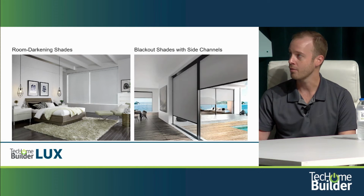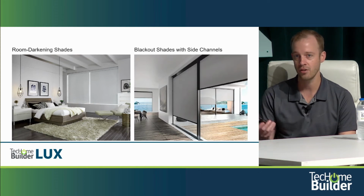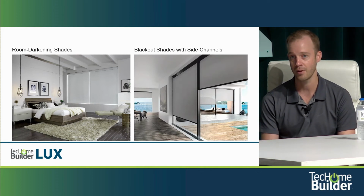Full blackout lives in side channels, right? So that's a conversation that also has to happen early on in the design process because these side channels a lot of times are architectural, right? They can be surface mounted, but most people prefer that they're recessed into a jamb so they don't have to look at them. But that is going to completely block out any light at all from coming into a room. And we see this a lot in primary bedrooms. We see this a lot in media rooms, spaces like that.